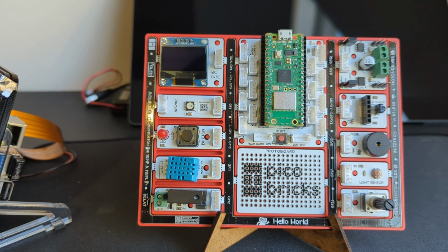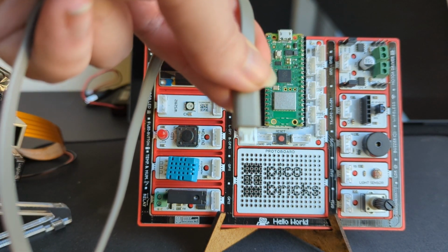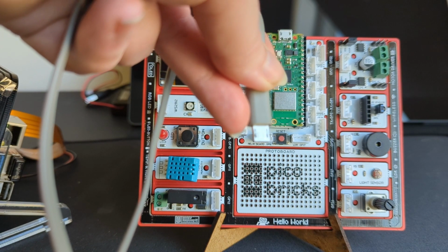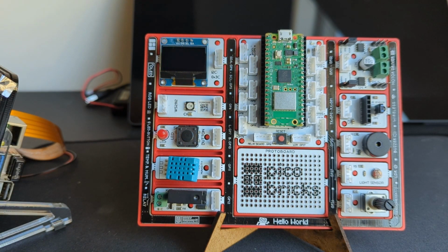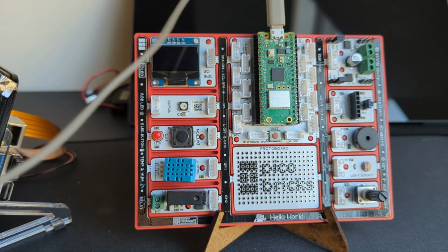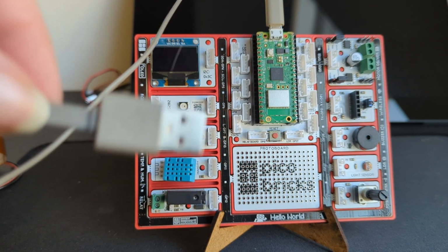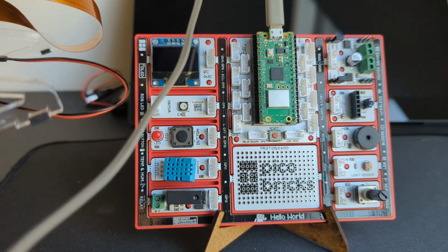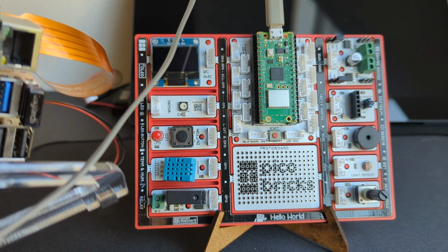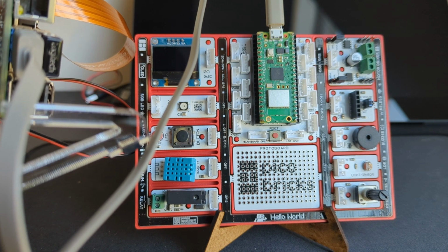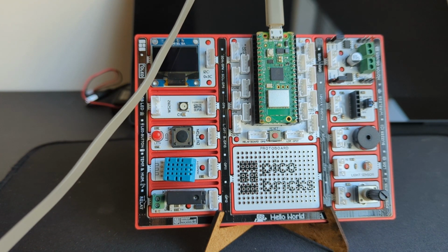Let's connect PicoBricks to our computer. We'll do this by taking the micro USB cable, and the small end here will go into our Pico board with the two little grooves pointing towards us. The other end of our USB cable, plug this into the computer. We're using a Raspberry Pi here. So it plugs in just like that, as it would any other USB port on your computer.